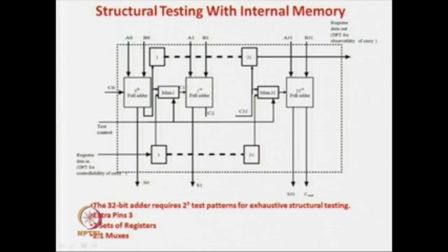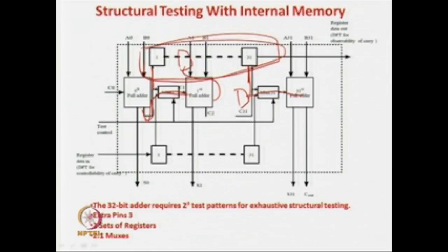We have a simple shift register. The intermediate carry output of this gate feeds the next level of the adder, for the time being forget about the multiplexer, and the same value is also written to a shift register. Again, the output of the next adder feeds another element of the shift register. Similarly, the output of the second last full adder feeds the last full adder and is also written to the shift register. So we have a 32 bit shift register here.